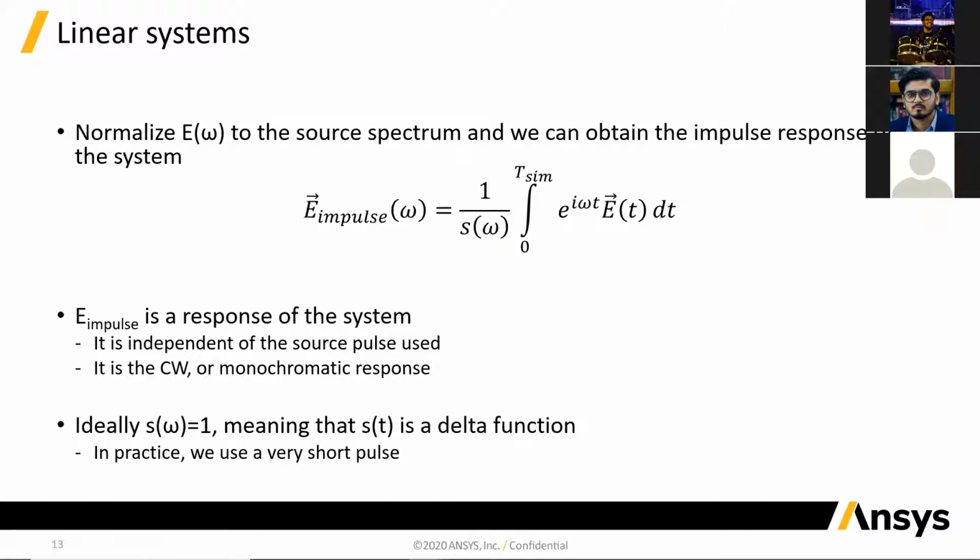And so if you have a particular device and you want to see how light is getting transmitted through it, what you want to see is the spectrum of transmission: at each wavelength, what fraction of the light is getting through and what fraction is getting reflected. This is how you can obtain the impulse response of your whole system. And this is done by default. So when you're using a monitor to see the spectrum, as we will see later on, these calculations are done internally.